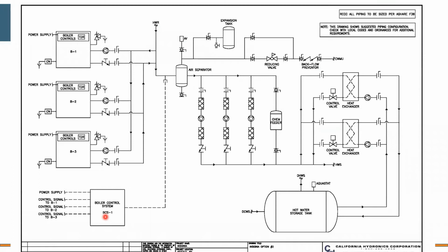How do I want to say this? This might be a little lengthy example, but kind of an important one. And then we'll get wrapped up here pretty quickly. Last week or two weeks ago, we were talking about boilers specifically. You can take boilers and you can heat domestic hot water. You can't do it directly. Typically, you need some type of plate and frame involved, which we might call an indirect style heat exchanger.